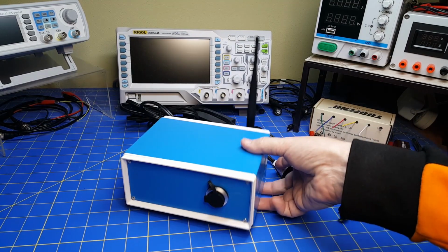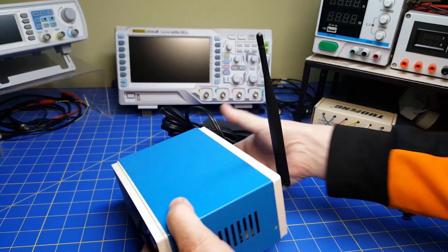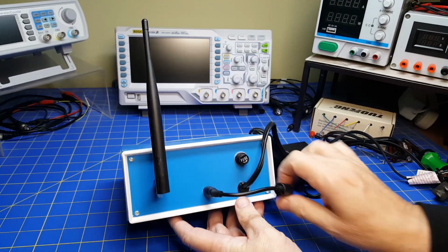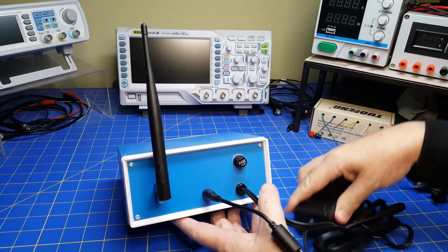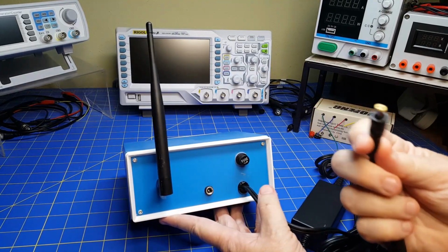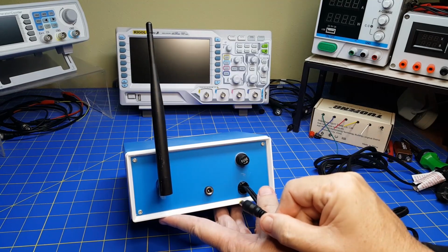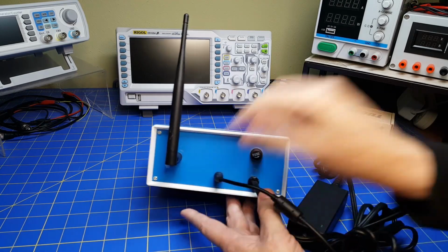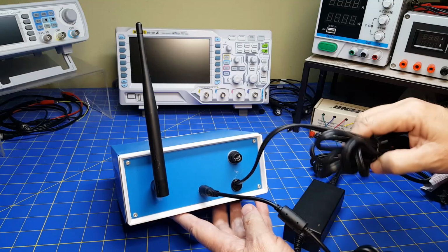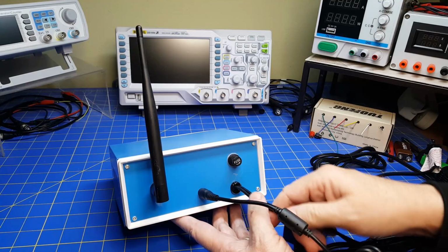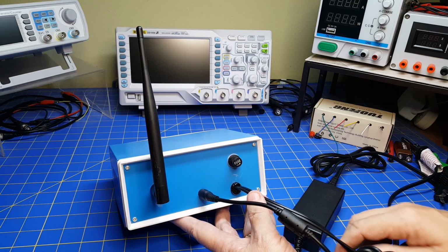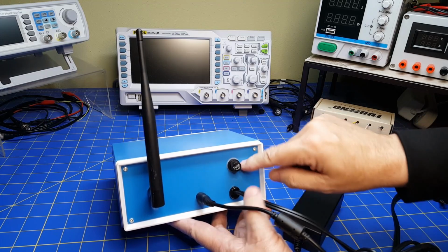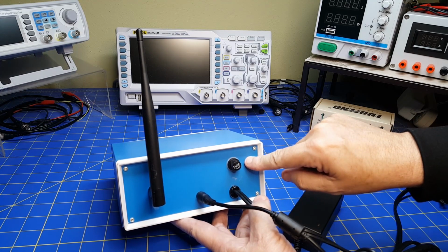Okay, so here's our box, and let's first take a look at the rear. I've got the antenna right here, and we've got two inputs. This one on the left is the barrel jack that is going into the Arduino Uno, and this is where we get the 9 volts coming in to power it. And here is directly from the wall outlet going through a strain relief, and this is going to go into the transformer that's going to give us our 12 volts. And then we've got the fuse here. I've got a 1/2 amp fuse on the primary of the transformer, and that's about it.